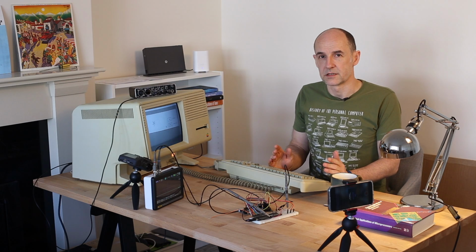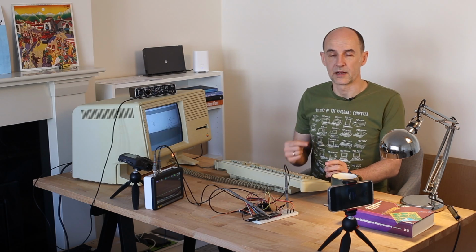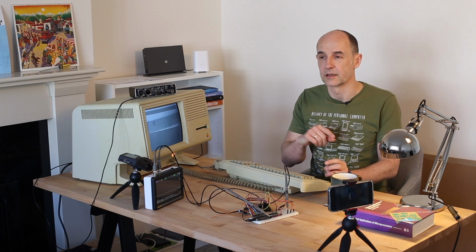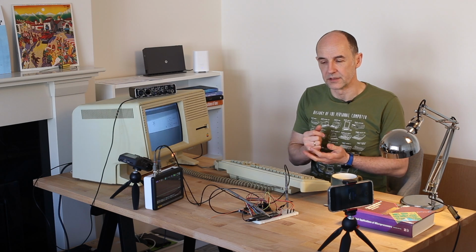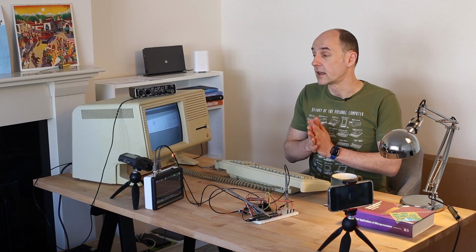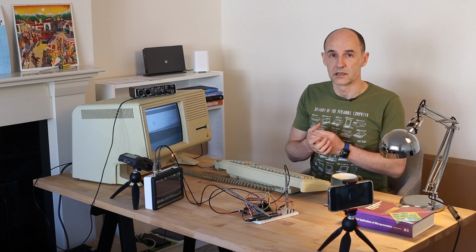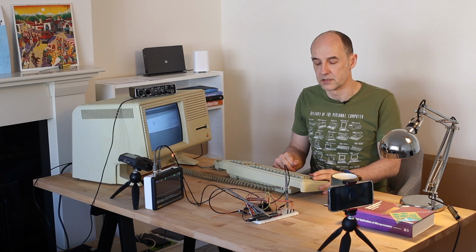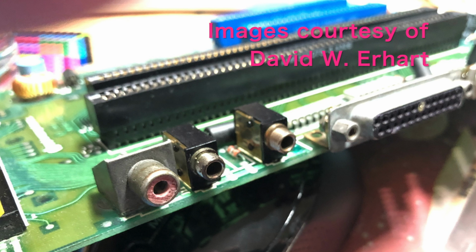Apple Lisa was meant to have a CVSD chip, which would take the signal, the pulse train from the 6522, and would do something more with it. It would create an arbitrary wave shape out of it, and only then output it to the amplifier. CVSD chips are used mostly for speech encoding and decoding, and Lisa was meant to have that capability as well, digitizing speech and playback of digitized speech. It even had input and output audio jacks in the original pre-production version, which was later dropped in the production version.